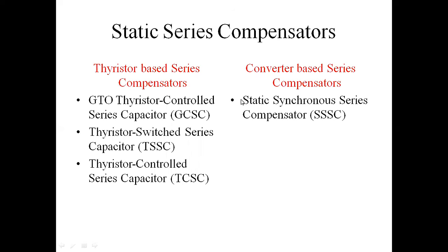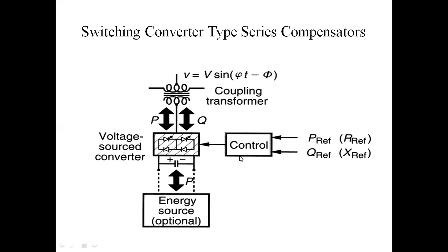SSSC means static synchronous series compensator. This is the controller. This controller has P reference and Q reference. P reference means the active power reference, and Q reference means the reactive power reference. When the energy source is not connected, the active power P reference is 0.